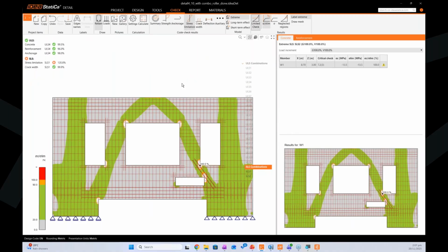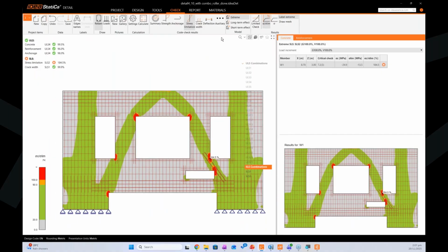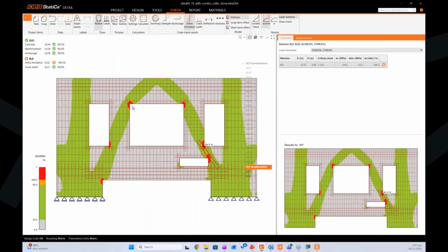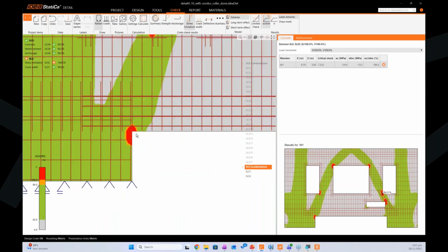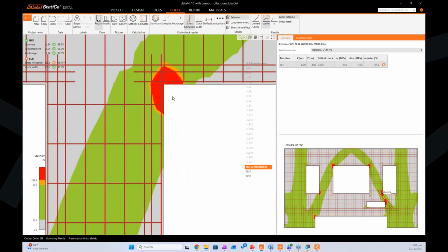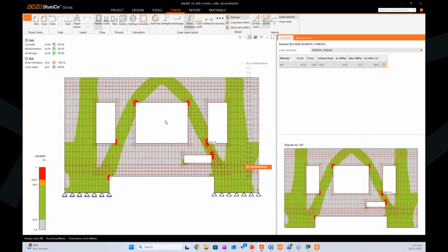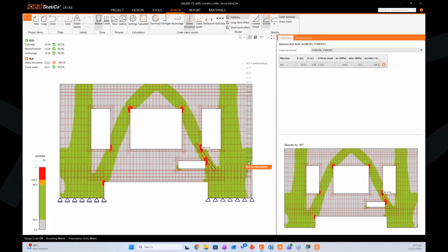Okay, just give me 1 second. Okay, so basically, as you can see, the stress limitation failure is actually happening on those corners, this corner. So I would categorize this as a stress singularity instead of stress concentration.